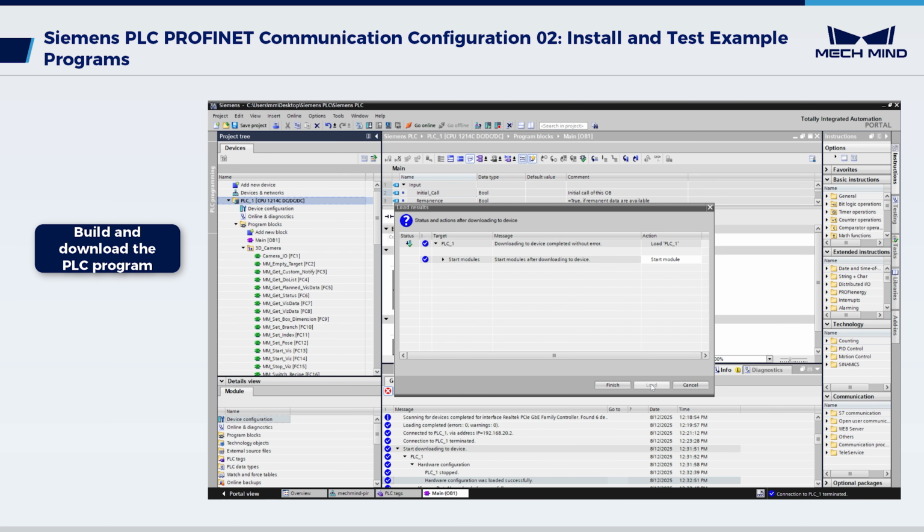Finally, test the PLC program to trigger the Vision project and receive the results. In this scenario, the eye-to-hand camera setup is used, with a single Mech-Vision project. Thus, the PLC only needs to trigger the project and obtain the Vision results.